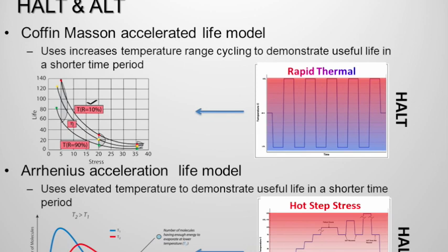Well, this is very valuable information when setting up an accelerated life test, because you don't want the accelerated life test temperature ranges to go into that destruct range. Because if you're creating destruction by going to such far extremes that you're no longer modeling the wear out, you now have a data set that's effectively contaminated or could actually be dangerous if you try to make a life statement on it.